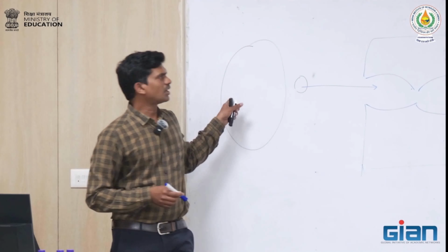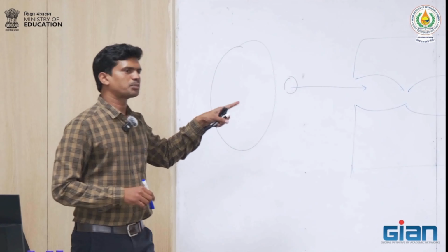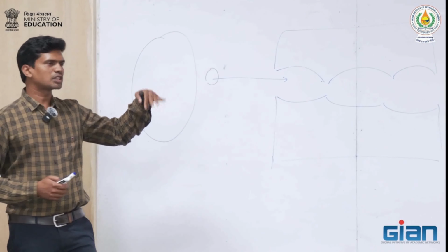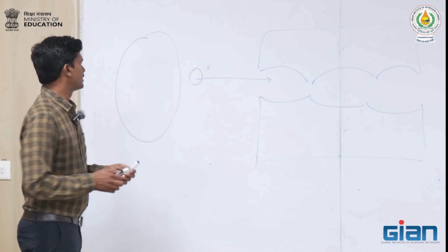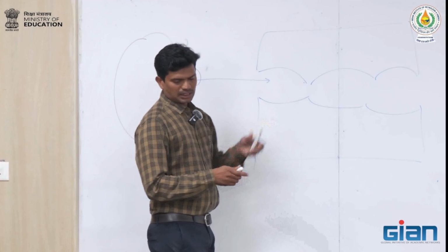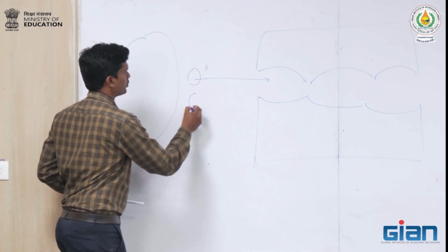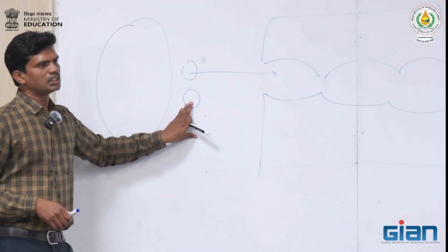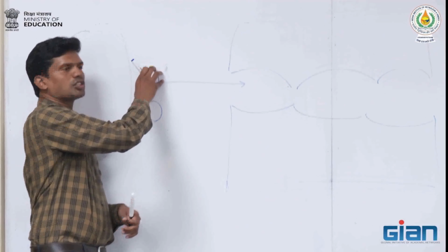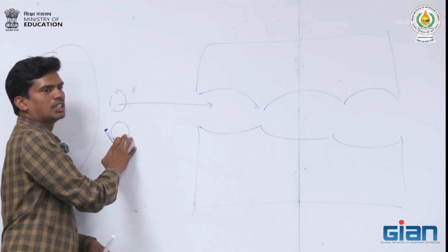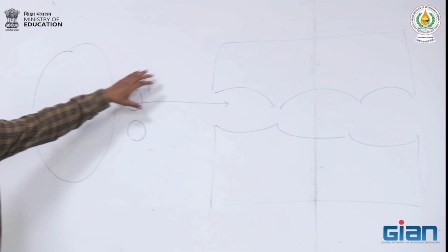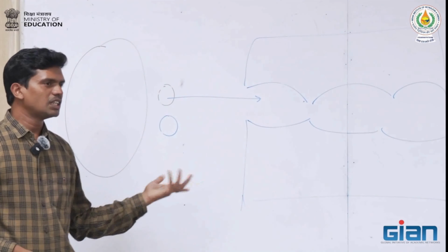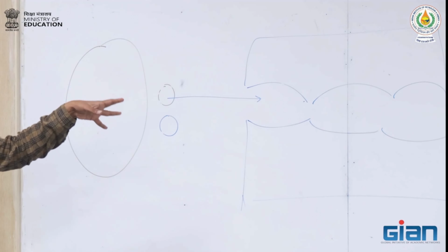So that process we still call adsorption, but it has to do with the steric thing. Okay. The second one is equilibrium, which we most likely do see. Whenever you have an adsorbent like this and two molecules which can both go through it, but the surface adsorbs this molecule more than that molecule. That means the interaction between the surface and this molecule is more than with the other. So this will go and sit on the pore surface, and fewer of the other molecules will sit on the surface. That is the second kind of separation, called equilibrium.